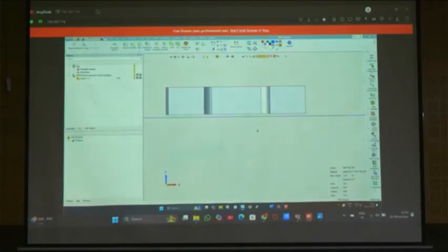That is why. Suppose here I kept it, I have designed with 10 mm, but your tensile ASTM E8 standard tensile sample will be 2.5 to 3 mm thickness. Suppose you have designed with 3 mm, you need exactly 3 mm output, or 2.5 to 3 mm output, since powder limitation is there. So for that we are adding a support in between. And if you are adding a support, the SLM parameters for the support structure are different, and the heat accumulation will be more, and we can get a good print if we are applying a support, be it a solid body or be it anything.